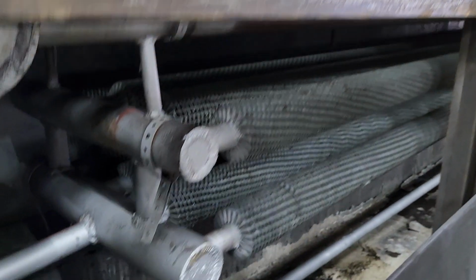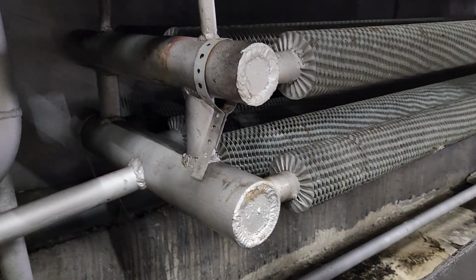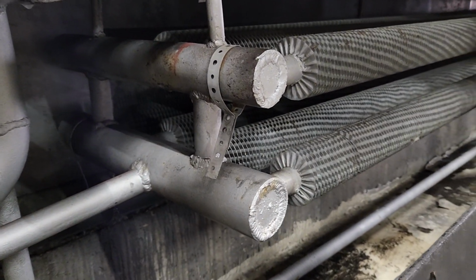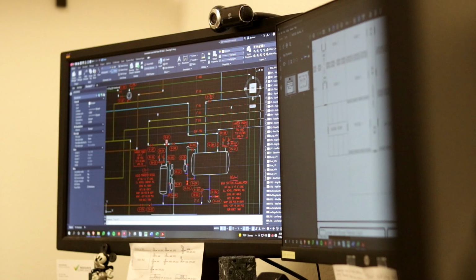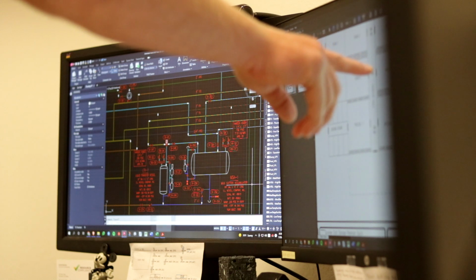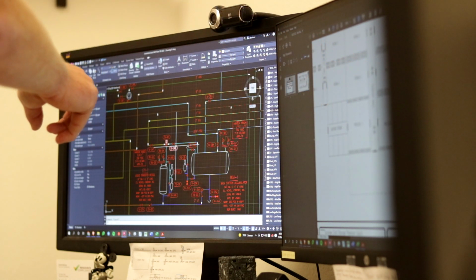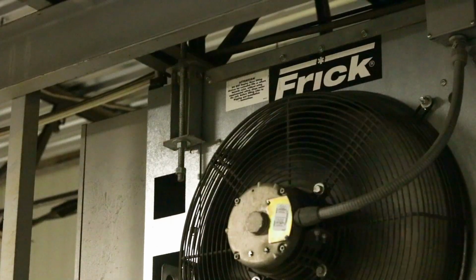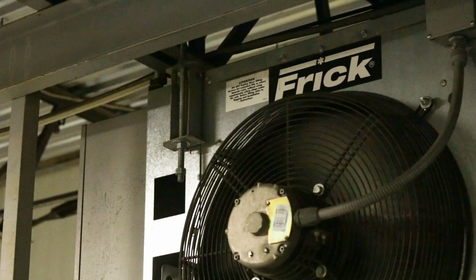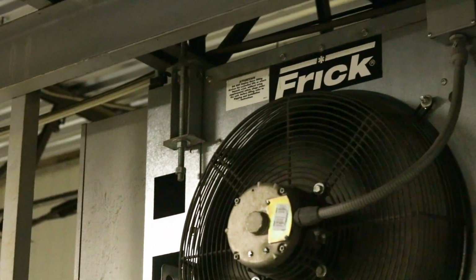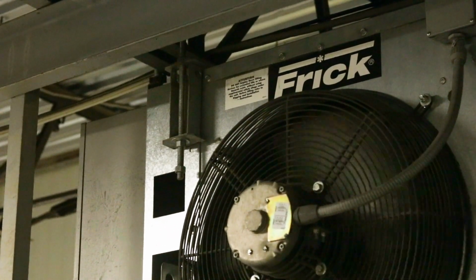As this process repeats, the result is a natural circulation of air without the assistance of fans. As you might have imagined, however, natural convection using bare pipe coils was not an efficient means of cooling. Engineers discovered that the rate of heat transfer is correlated with the heat transfer surface area. To take advantage of this, metal fins were added to the pipes, substantially increasing the surface area of the evaporator. However, while the fins increased the surface area, they also restricted air movement. To address this, fans were employed to force air through the evaporator instead of relying on natural convection.